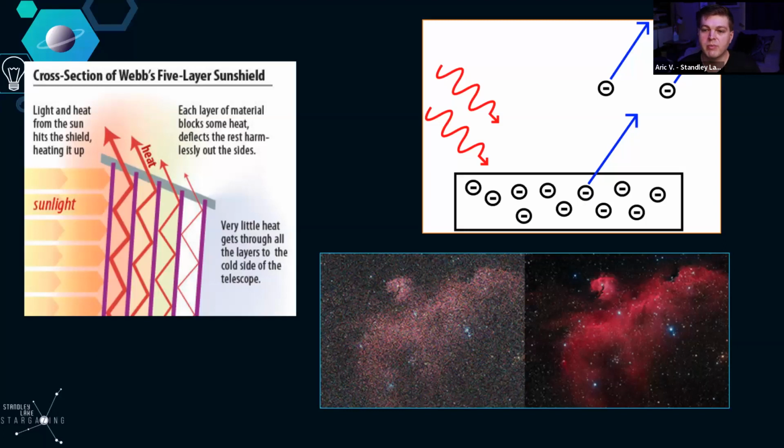Back to the bottom image now. When we look at that, we get all this extra thermal noise. That's just heat generated by the detector, by the different components in it, the battery even, or the screen on the back of the display if it has one. All of that heat is emitting infrared light, and that's registering on the detector, but we don't want that because it's not part of the signal that we're interested in. So now we have to find ways to shield against that.